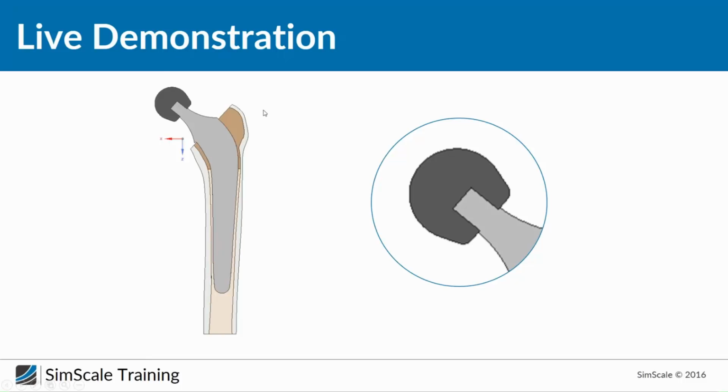And let's take a look. So this is a cut through our 3D model. And here a very important and big difference is that this model is made of different parts. We have at least 5 different solid bodies which are connected. And therefore we not only have to define what are the material properties of the single parts and how they are interacting with the environment, we also have to describe what is the interaction between the different volumes. And in this case, we're talking about contacts.